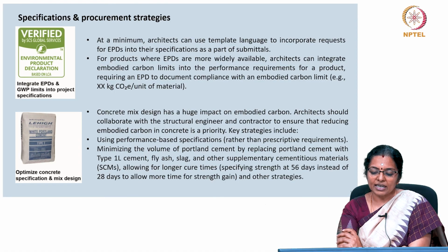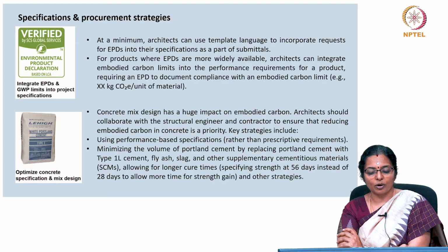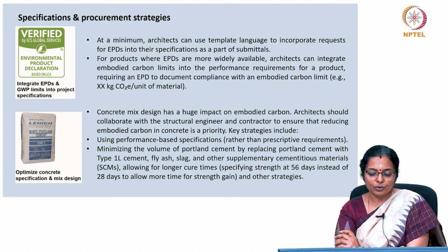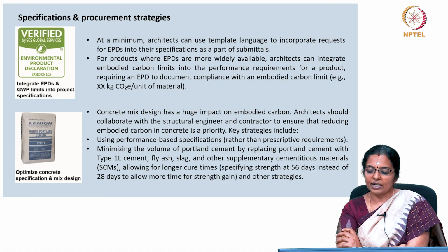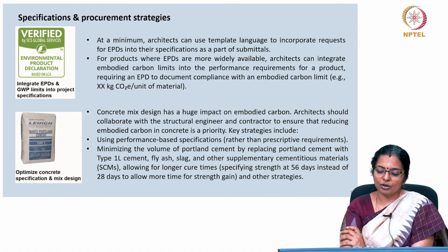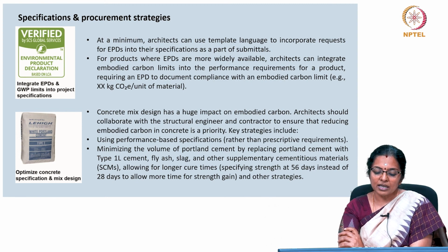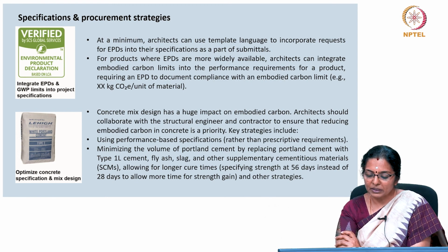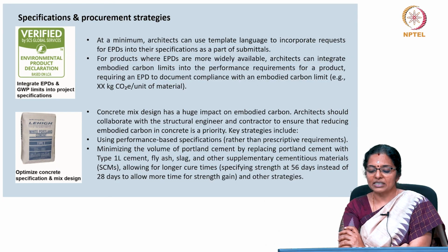Concrete mix design has a huge impact on embodied carbon. Architects should collaborate with structural engineer and contractor to ensure that reducing embodied carbon in concrete is a priority. So, what are the strategies? Using performance based specification rather than prescriptive requirements.